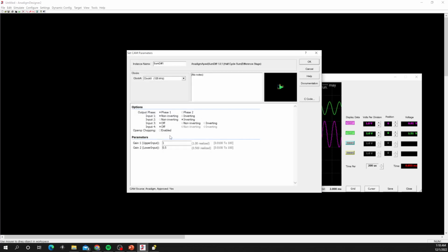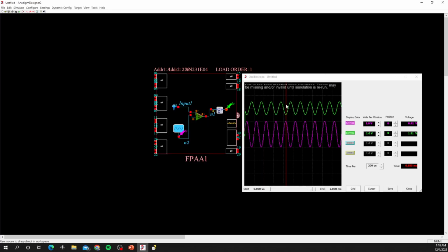And here, since we actually use an inverting and half of it, that means after we halve it, the peak amplitude, if you look at the output, from the green one, is 1.5 to 2.5. So peak to peak is 1 volt, so the amplitude is half a volt, right?